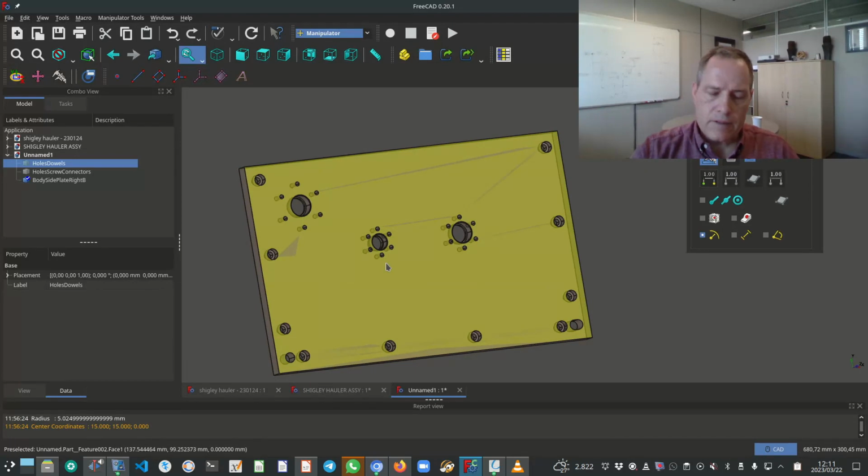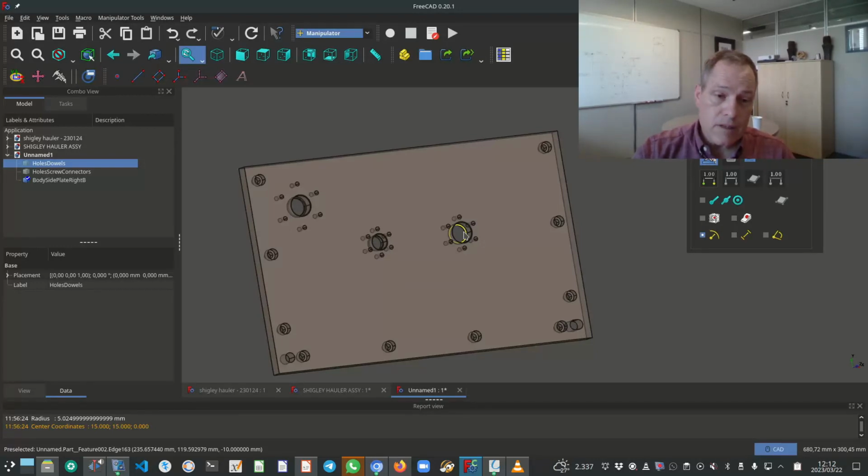Okay, the first important thing to note is that these side plates will be manufactured from polycarbonate, and the polycarbonate is applied in standard thicknesses. So we will use a 12 millimeter thick polycarbonate plate. Now, having said that, I've spoken to the supplier of this 12 millimeter thick polycarbonate plate.